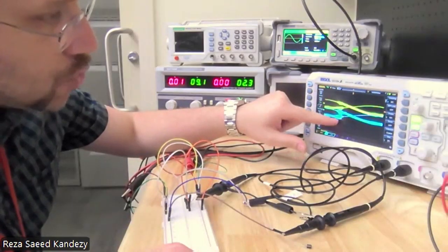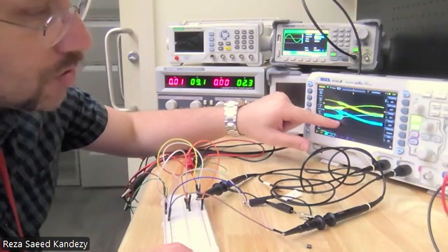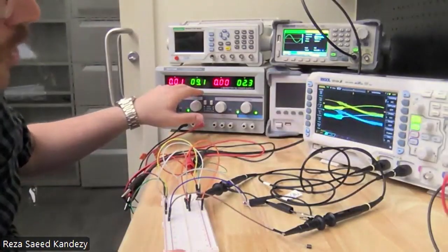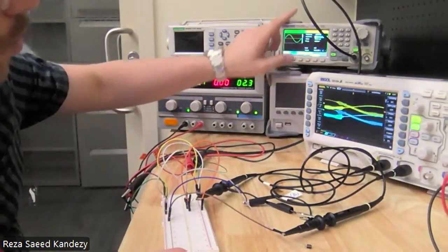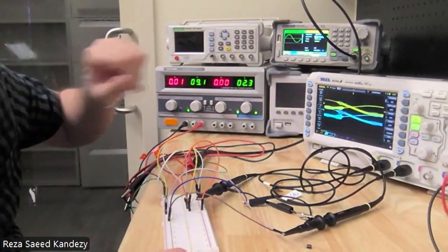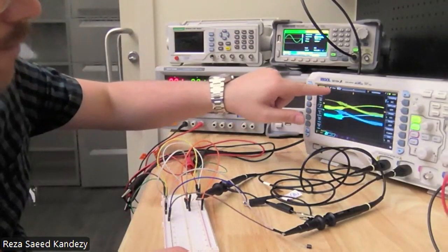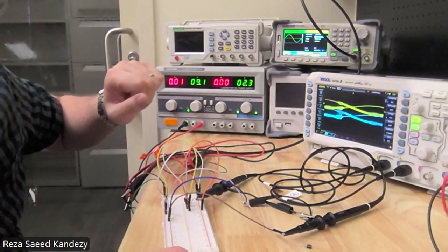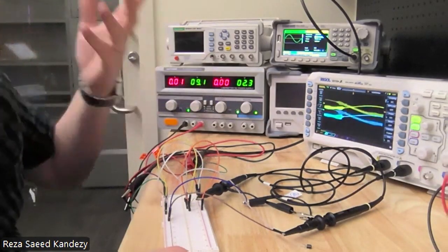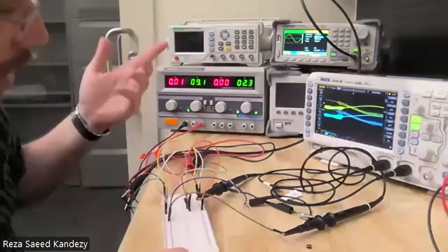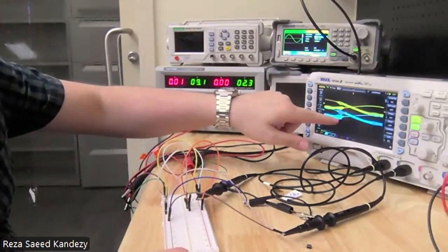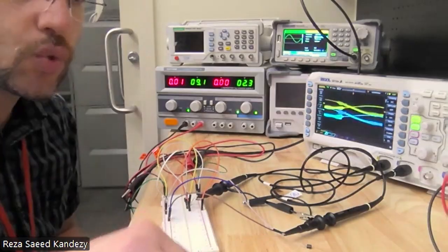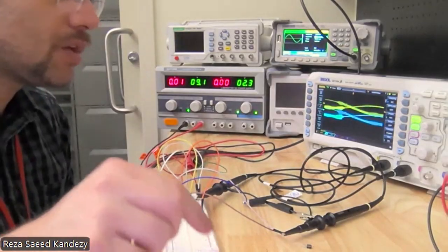So my time distortion duration here for this specific circuit, with a 9 volt voltage source and a 3 volt 1 kilohertz sinusoidal signal, is 50 microsecond in my output waveform. And my load is 1K. So this is how we can measure the time duration of the distortion in our circuit.